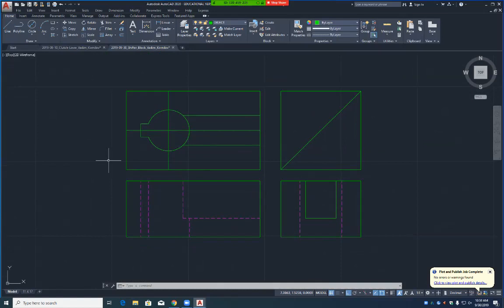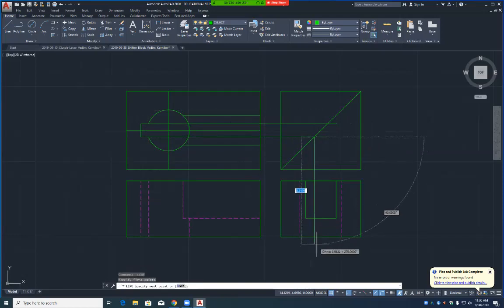Now we've got to draw our keyway over in this view here, right? That makes sense? How you going with that? All I'm doing is copying, space, space, copy, space, space. That's all I'm doing. So copy this line from here over to here. Why take time to trim that? That's what I just got finished saying. So copy this line here.